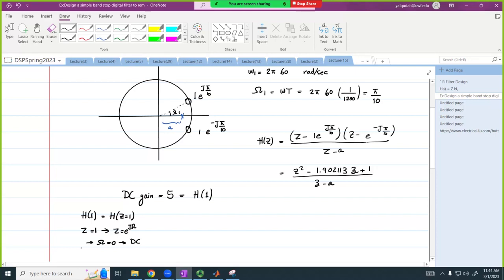Keep that in mind. I mean, we've seen it when we looked at the simpler filter. The gain of the filter at this frequency, I substitute z equal to 1. What is the gain of the filter at very high frequency? What did we substitute for z? Negative 1. Z equal to negative 1 means omega equal to pi, which is the highest frequency. Is that clear?